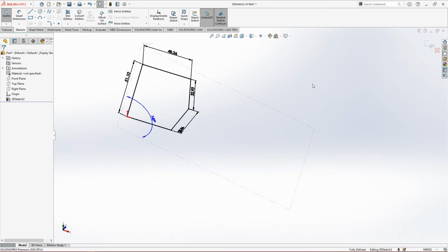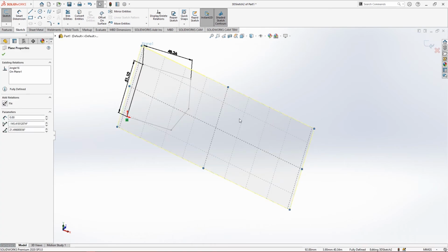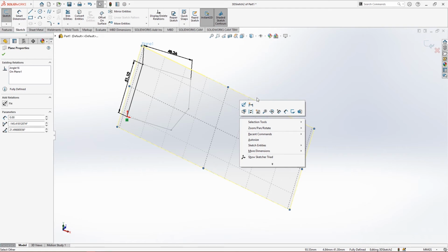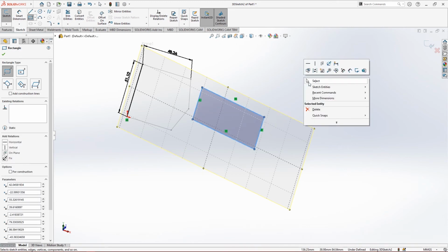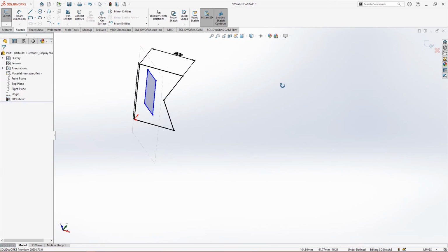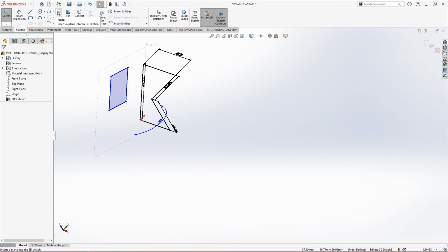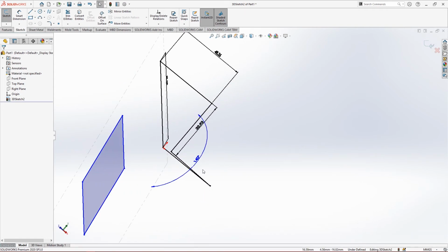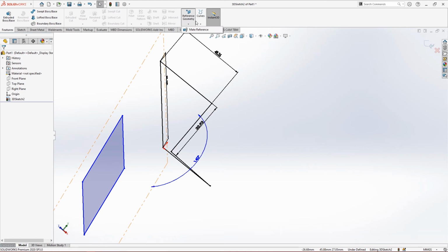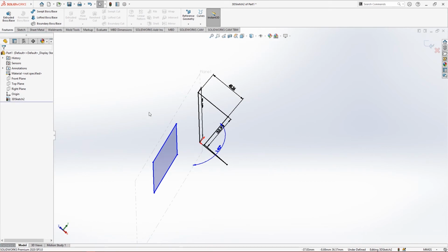So we can make so many planes, and if you just want to get out of the plane, we can double click anywhere. And if we want to sketch on this plane, we can double click on it, and when the plane is active, the color is yellow, and you can draw on it anything that you want. You can draw it and you can get out of it. So this is how you can add a plane. Adding a plane in 3D doesn't require all the constraints to be satisfied. You can even give dimensions to this plane. For example, I have defined an angle. These dimensions cannot be given to the planes which are added by reference geometry. So this is how we can play with the planes.